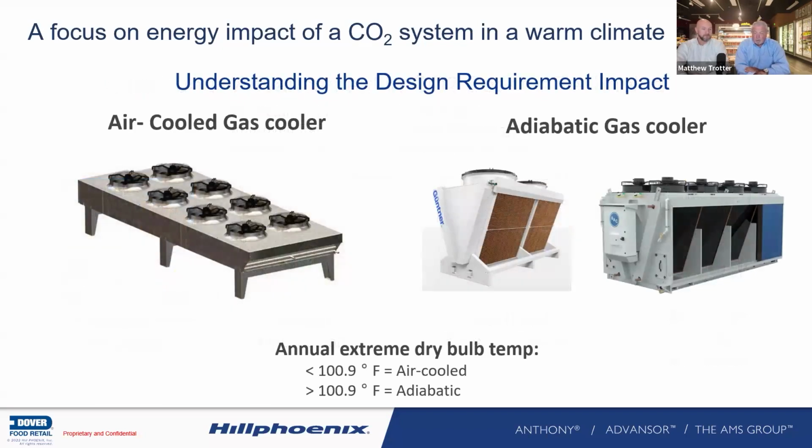So let's first take a look at the gas coolers. Two types of gas coolers. We have the air-cooled gas cooler and we have adiabatic, where again we use the pads. So looking at an air cooler and we look at the extreme dry bulb condition, if you're under 100 degrees or 101 degrees as shown, we're allowed to use, or we have an option to use air-cooled. Now, keeping in mind that the air-cooled in a cool climate works very well because we have the temperature differential.